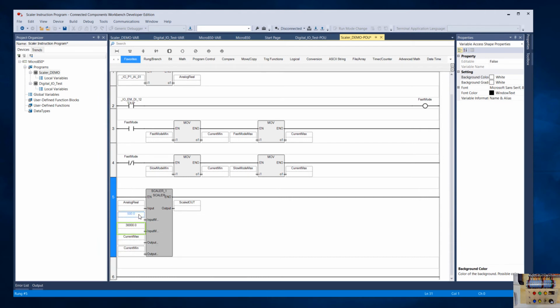So, and let's say, get that back to 0. Oops, 0.0. So now our range is roughly 0 to a little less than 5 volts. And that way our output scale is maximized to that 0 to 5 volt input. And that works fine. But what if something happens to that input variable, the voltage supply gets increased or whatnot, and all of a sudden instead of going 0 to 5, it goes 0 to 7 or something. Our scaled output then would go up by a factor equivalent to 7.5 divided by 5, right?